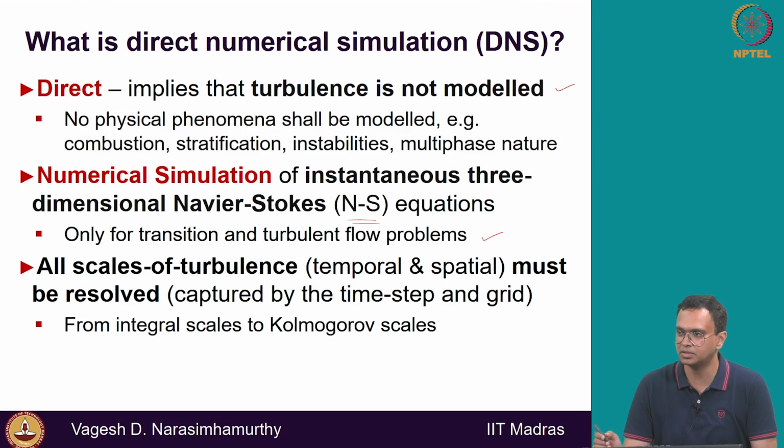Indirect method implies turbulence modeling, right? Suppose you have a turbulent flow or a transitional flow, you can go ahead and use Navier-Stokes to solve this, or you can use some RANS models to solve this. Whatever the accuracy is, you have an option. But when you are solving for a laminar flow, there is no indirect method. There is no modeling idea there, and therefore DNS.